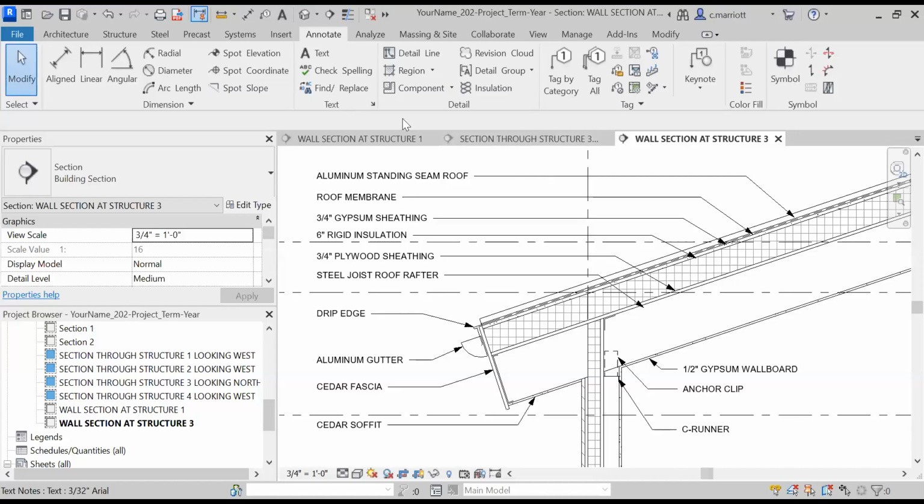So these are the components that need to be identified with your annotations. Keep in mind, we like to start with the outermost material and continue to work our way into the assembly. And then sometimes you need to reference or identify components from the opposite side. Maintain alignment on the left edge. Make sure all of your notations are capital letters, like I have here. And always bring a horizontal out before you break into a diagonal line.